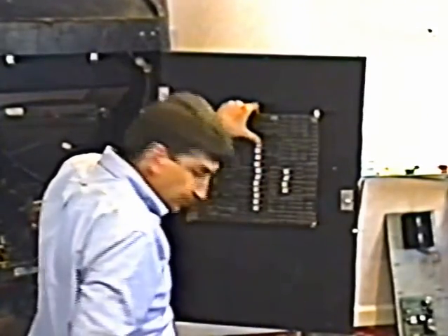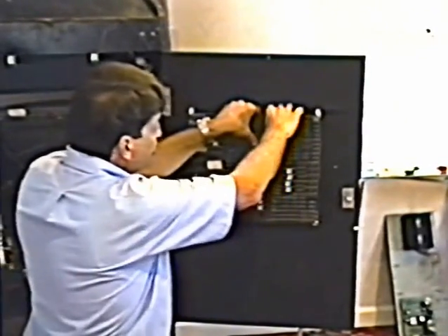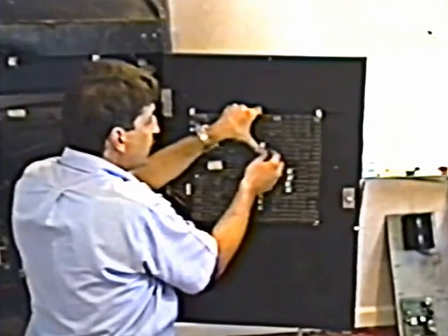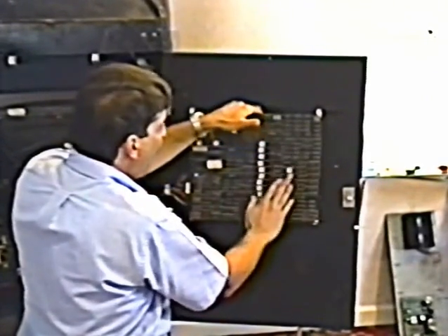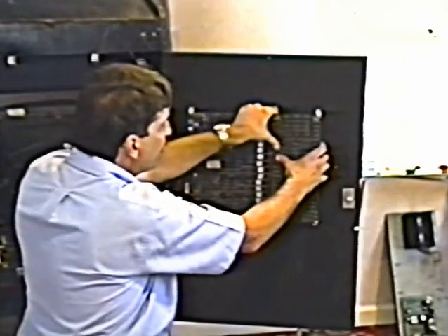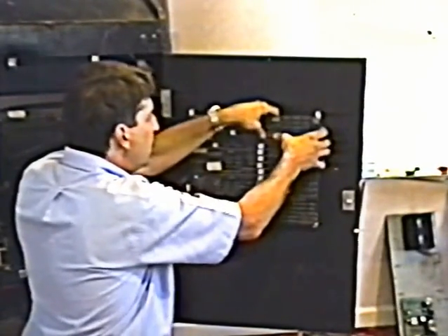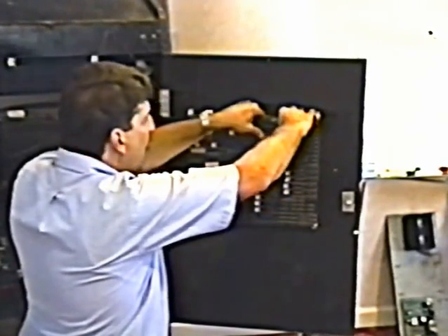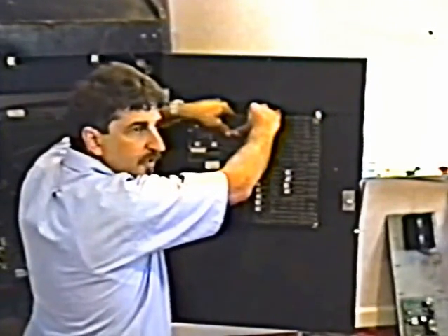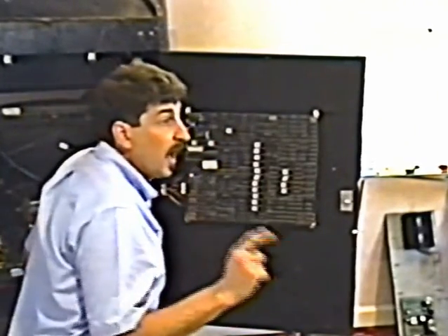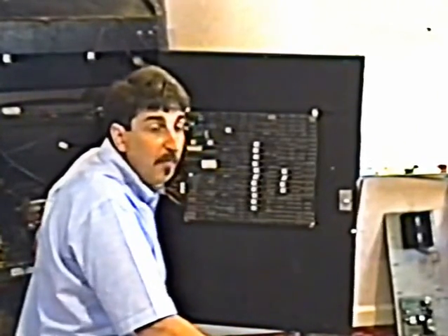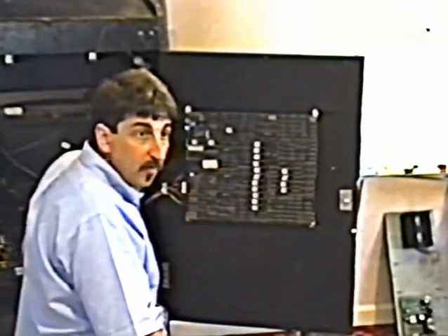Anyway, one at a time, you pull out the integrated circuits carefully, prying them out with a screwdriver, and put them all back in. It'll take a little bit of time, but for instance, on Pole Position, which we operate a lot of, I have to do this about every year, pull all the chips out and put them all back together again. That solves a lot of board problems. About 20-30% of my board failures, that's all I do.